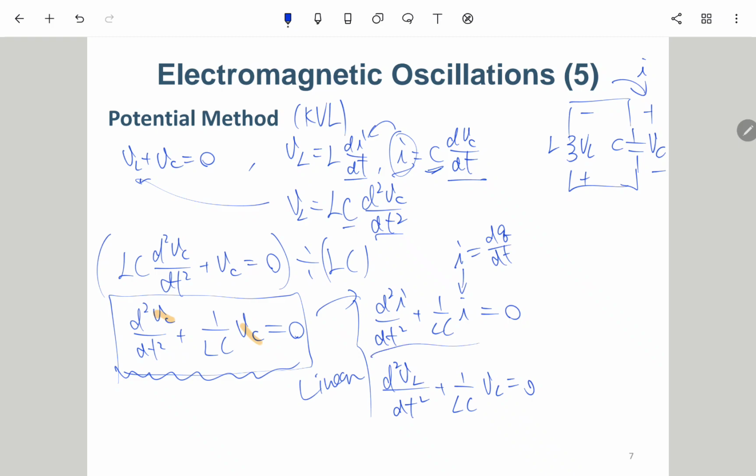And then, you can just put I to be dQ/dt here. So it becomes a third derivative and a first derivative, and then you can cancel one order, so that it becomes an ODE for the charge. So that's the interesting part for the linear system. We can derive the equation for this LC circuit, which is a second order ODE.